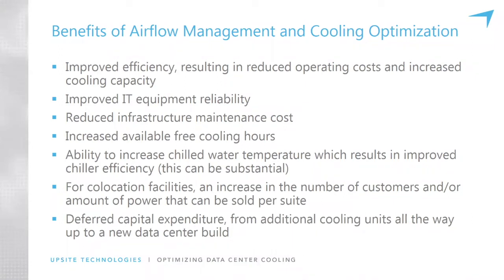We haven't left the computer room in these conversations, but making improvements to the airflow management and the cooling optimization in the computer room creates the ability to increase the chilled water set points, which can have a substantial impact on the operating cost of a facility. Chillers, if a facility is using chilled water systems, those chillers consume a great deal of energy and they become more efficient the higher the chilled water temperature.